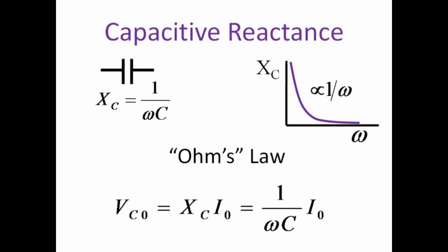The capacitor responds differently at different frequencies, with reactance rather than resistance. At low frequencies, the capacitor acts like an open circuit with infinite reactance, but at high frequencies, the capacitor's reactance is reduced, and the capacitor becomes innocuous, like a bare wire with no effect on the circuit. The reactance of a capacitor is inversely proportional to the frequency.